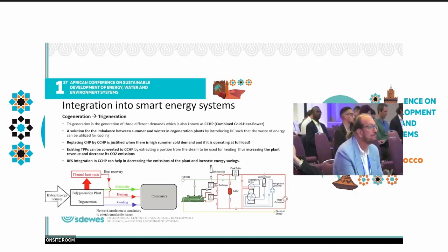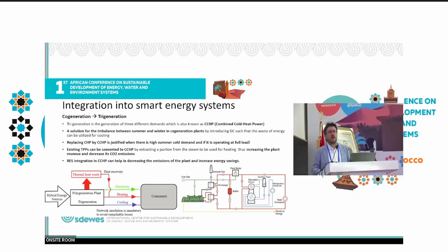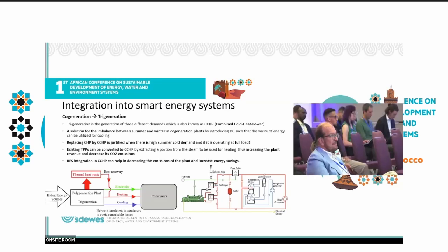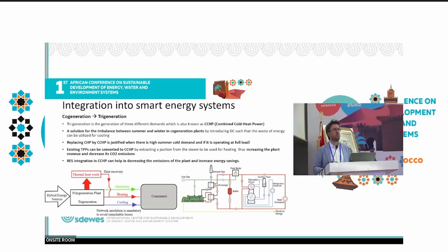Of course, when it comes to cogeneration, you have this gap between summer and winter in heat production, and you need to find different ways to utilize that heat. Upgrading cogeneration to a trigeneration plant increases the efficiency of this type of system. The negative side of these systems is usually that cogeneration plants use fossil fuels like fossil gas. But from a renewable point of view, we can discuss future cogeneration plants running on renewables from biomass, biogas, any kind of synthetic fuels and so on. So in order for cogeneration or trigeneration plants to be viable as a part of future district heating and cooling systems, this step will probably be very much necessary.